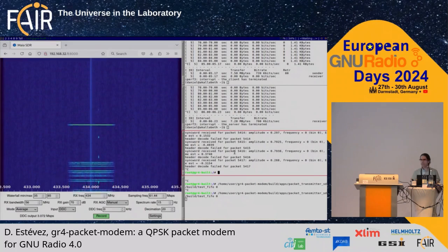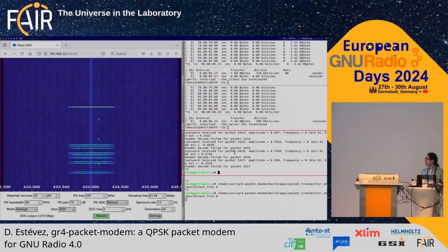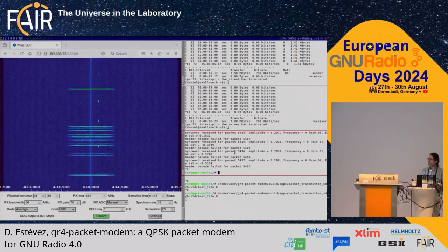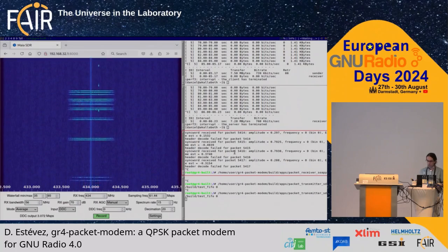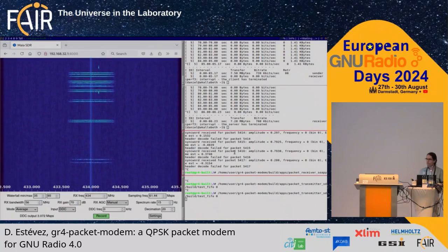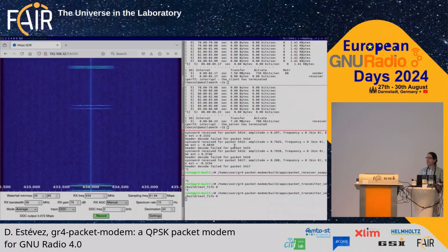Daniel, hi. Can I ask something? That's great work, by the way. I'm just curious if you can start iPerf transmission again and adjust the receiver gain while the packet is coming, to see how much it can compensate for amplitude variation. Because I understand you didn't use any automatic gain controller or whatsoever, so it may disrupt the Costas loop. Within the packet, it doesn't compensate for amplitude variations.